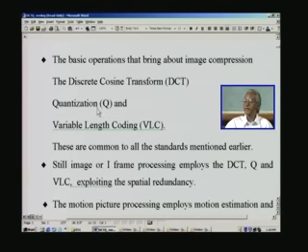In quantization we make an attempt to make as many DCT coefficients 0 as possible. The purpose of making them 0 is that we do not have to code the quantized value. This coding is done in Huffman coding or variable length coding, abbreviated as VLC, and what this code does is take the frequently occurring intensity value of any signal, which will get reflected as a DCTQ coefficient value, as the input.